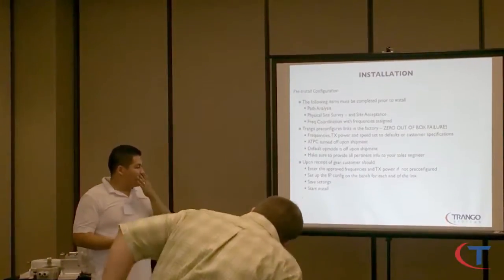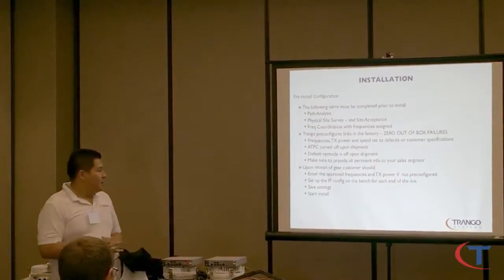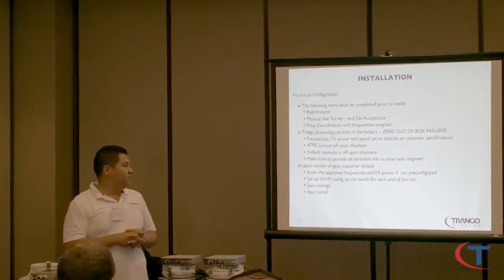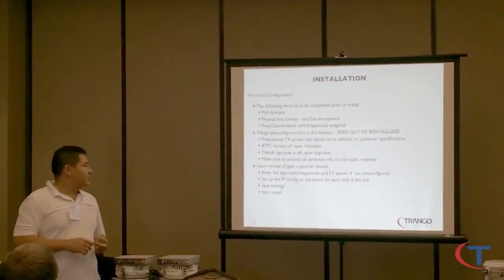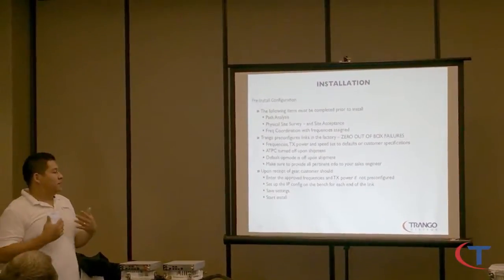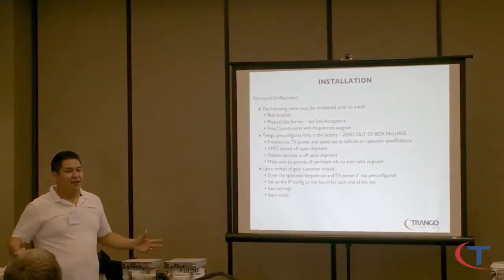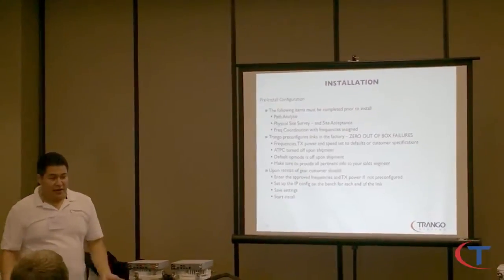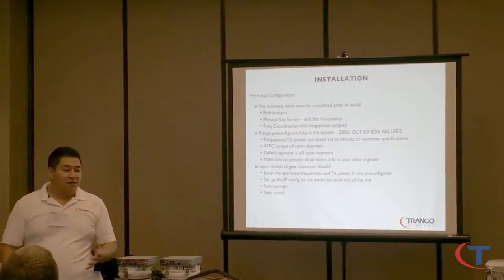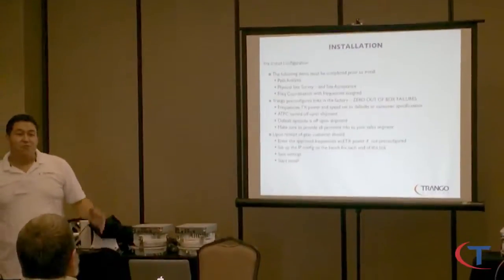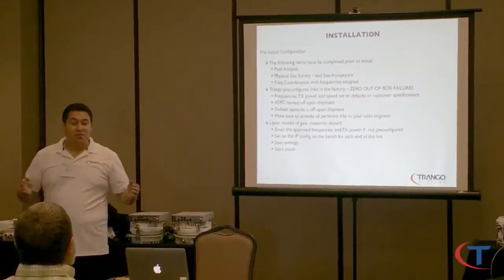Upon receipt of gear, customer should do what? Enter the approved frequencies and TX power if not pre-configured, set up the IP config on the bench for each of the links, save settings, and start installation. Again, number one thing of this training, if you remember my name, nothing, you hate me at the end of this training, remember, put it on the bench before you deploy it.